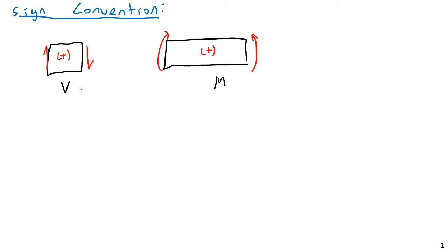So when students are first learning shear and bending moment diagrams and statics, this can be a bit confusing, I know. Because it's something students always struggle with when they first learn this stuff, because they see an upward arrow, they want to call that positive. They see a downward arrow, they want to call that negative. But when doing sum of forces on an end, sure, that'll work out. Upward will be positive, downward will be negative.